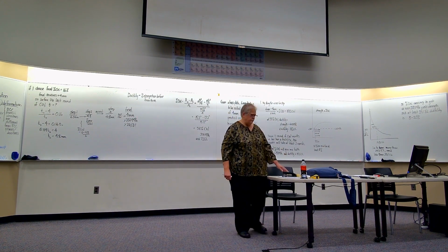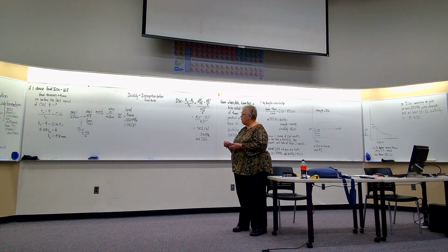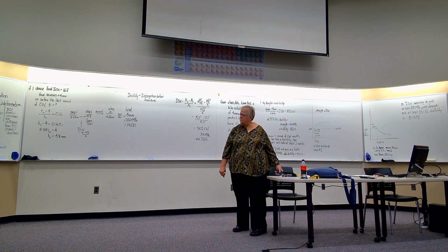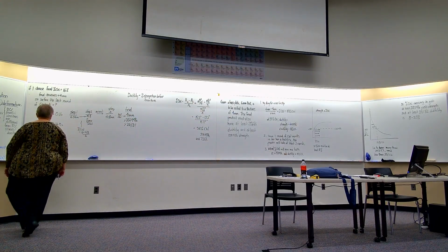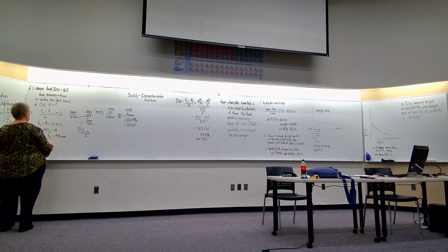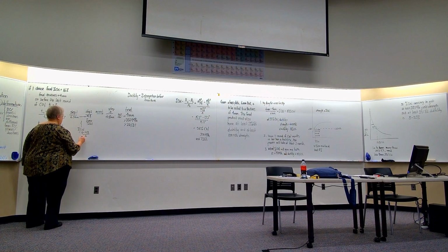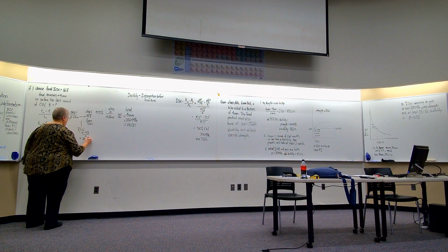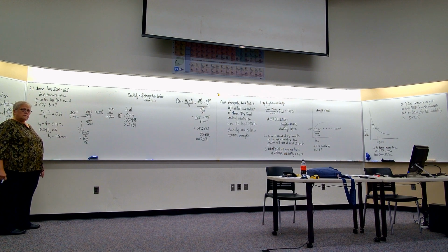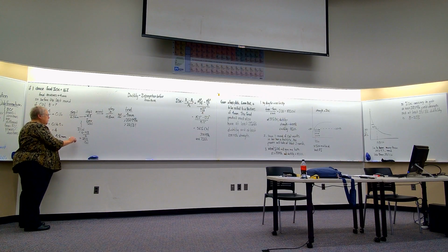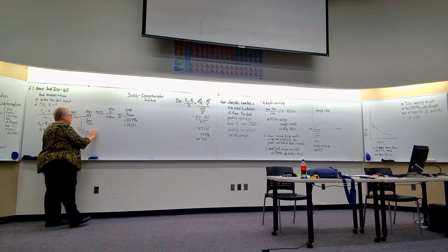Right? So my process is, take my 6 millimeter, take it down to 4.8, get rid of the cold work, and then my last step will give me the properties I want.